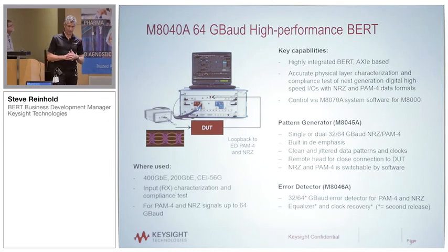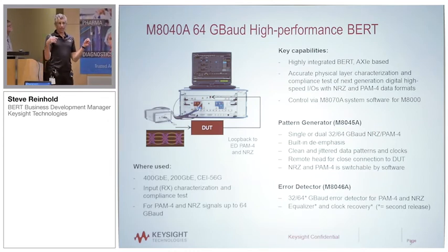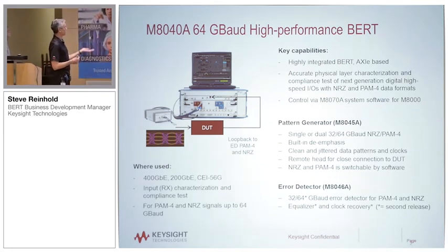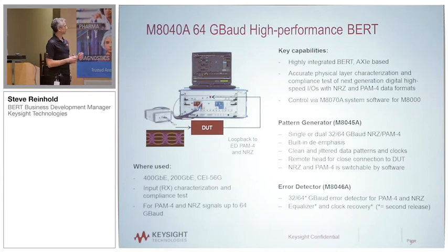In the past, people applied NRZ BERTs to create PAM4 signals, and it required a lot of external hardware. It was pretty complicated, with a lot of fiddly cabling and tuning of the timing and everything. But now we've integrated it, so it's really easy to switch NRZ to PAM4, with built-in de-emphasis and things like that.